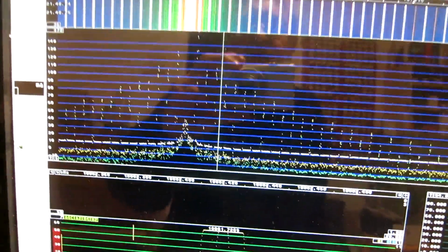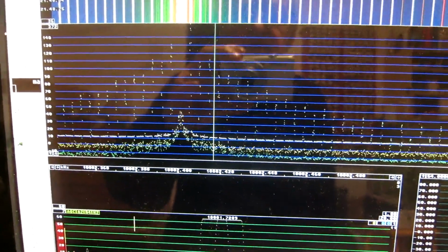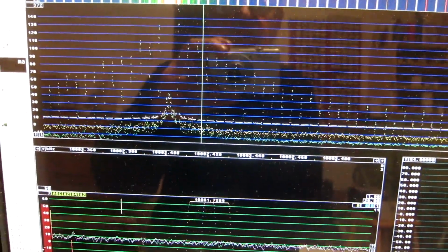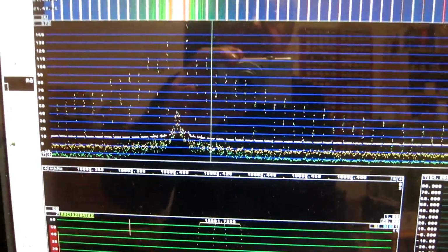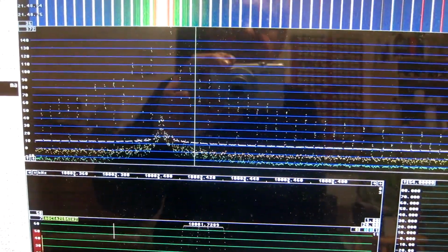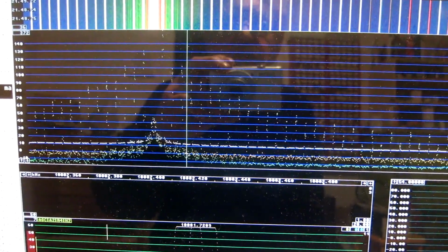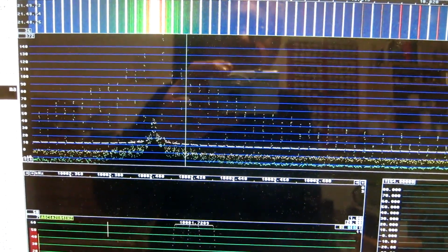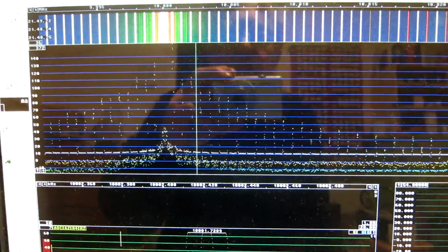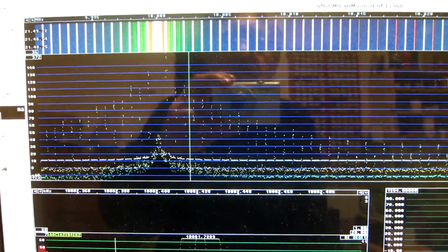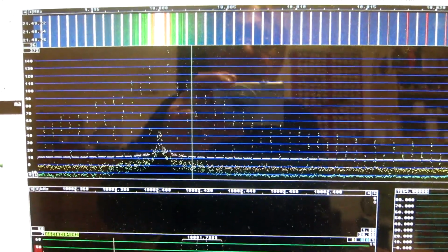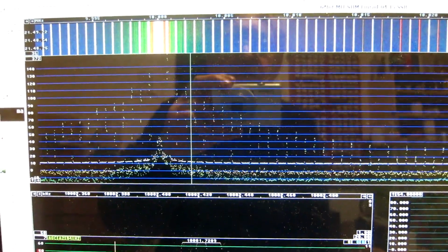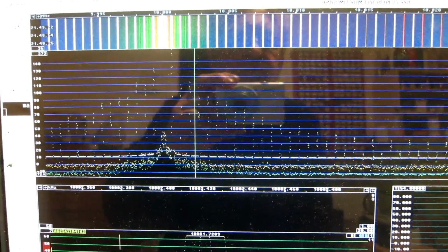I have added now a new version for the first FFT, using double precision floats for the FFT and for the window function in front of the FFT. The window is very important to have in double precision because rounding errors on the window would otherwise be correlated between the channels.